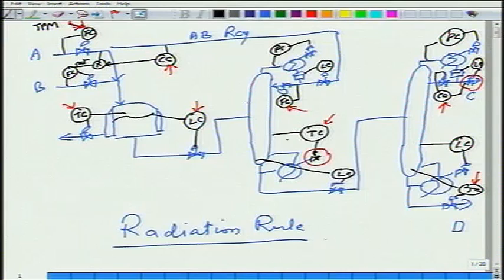this column, the recycle column, should probably be run at flooding, at or near flooding condition. Why? Because that would ensure that my recycle is as much as possible. If recycle is as much as possible, then recycle is mostly A. I want to run the reactor in A rich environment. The richer the composition of A, the less the side reaction. Okay. So what that essentially means is,